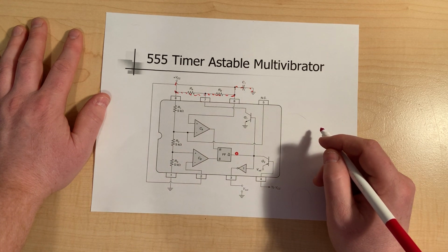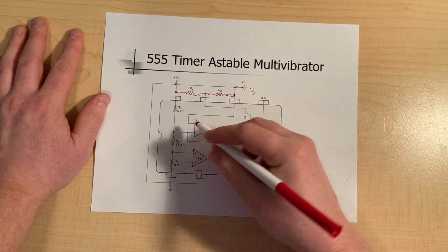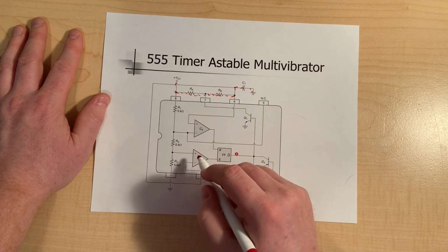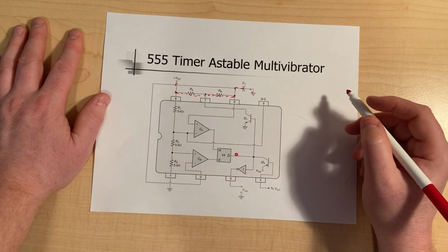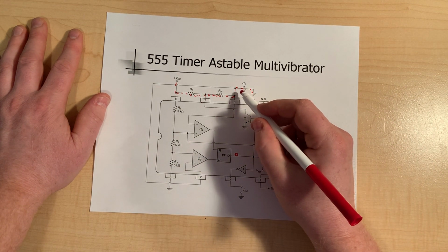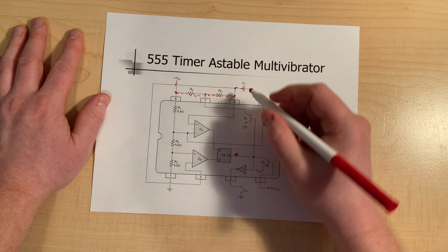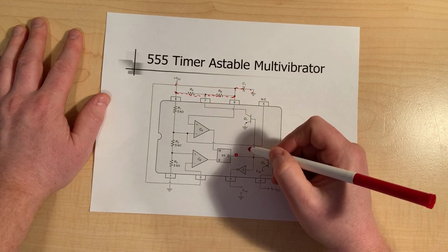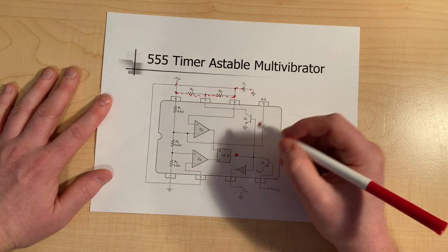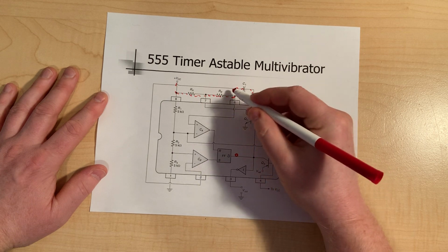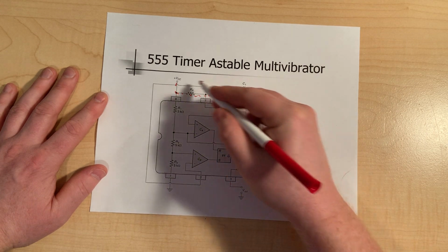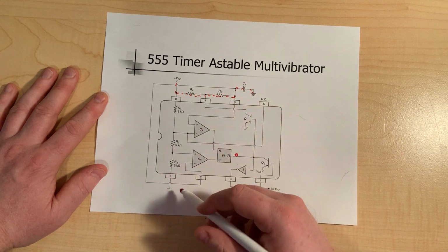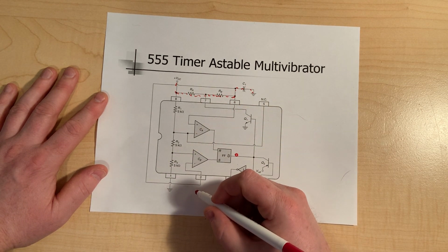Remember we have reference voltages set here and here. When it gets to a potential that becomes large enough, because it's across pin 6, it sets the potential for pin 6. So at some point pin 6 is going to be high, and notice that this ties to pin 2 on this side. So at some point pin 6 and pin 2 are both going to be high.